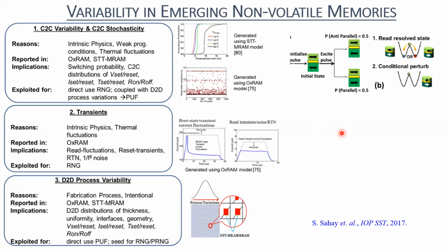So at the end of 1 million cycles, you need to give it another seed, which is called a random seed. Depending upon that seed, the state of that LFSR changes, and then it again produces a set of new 1 million numbers, which cannot be recognized if you know the previous 1 million digits coming out of your RNG. That is why you need this seed.